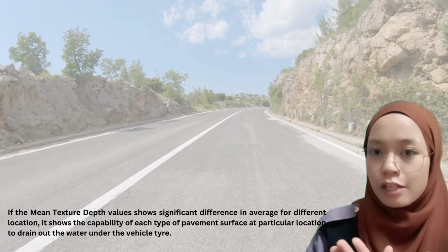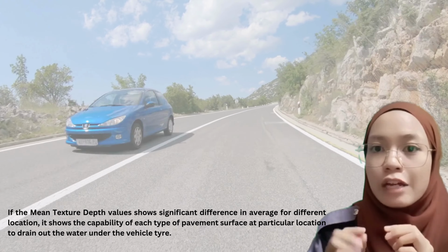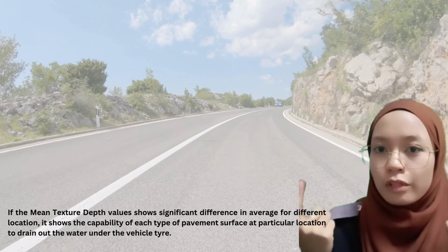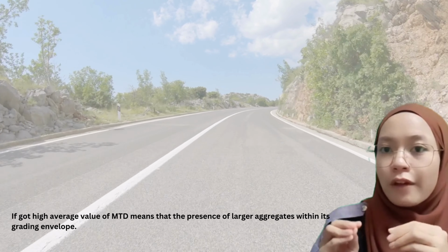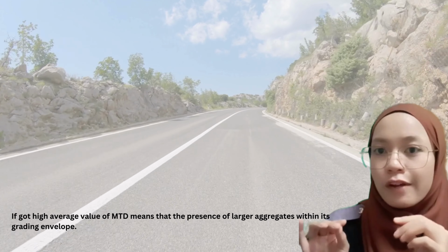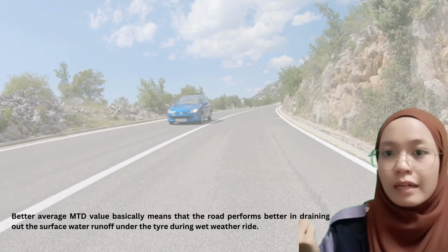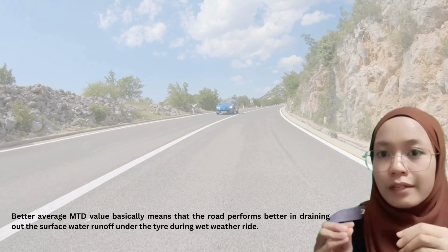If the mean texture depth MTD values show a significant difference in average between different locations, it shows the capability of each type of pavement surface at a particular location to drain out water under the vehicle tire. A high average MTD value means the presence of larger aggregates within its grading envelope. A better average MTD value basically means that the road performed better in draining out surface water runoff under the tyre during the ride.